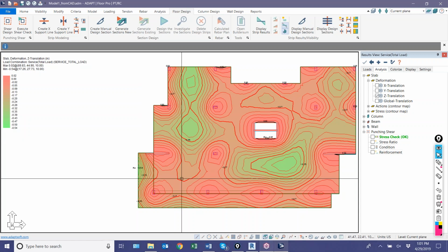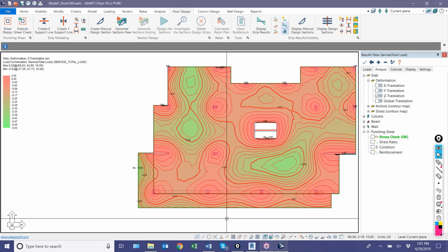Okay, so we're going to stop there for today. Thursday is the part 2. Thursday we're going to set up our design strips and then start modeling the post-tensioning for the slab. We'll model the PT. What we'll likely do is model strips, show an example of modeling the banded tendons and distributed tendons, and we'll advance the model with all tendons and show the process of results and checking stresses, flexural stress, precompression, balance loading, and then final long-term deflections and reinforcement results on this Thursday.